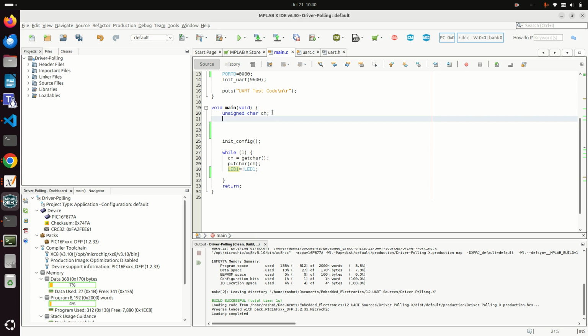For that I am going to declare one variable, unsigned int wait, and initially I am considering this equal to 0. Here I am going to write a delay which is a non-blocking delay. If wait-- equals 0, then what will happen?